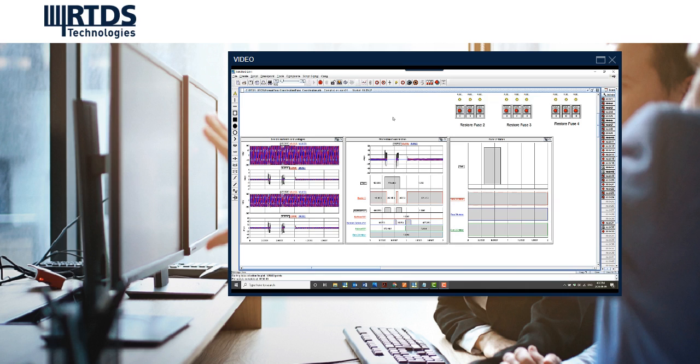You can also see at the second reclose attempt that the instantaneous element has been disabled and the feeder protection has been switched to the time overcurrent element. So the coordination of the protection in this way has prevented fuse 2 from blowing in this case of a temporary fault.